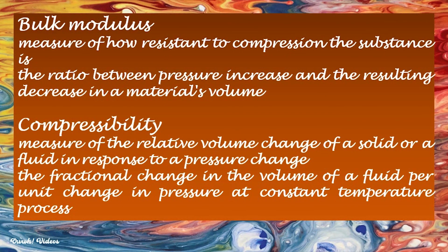Bulk modulus, a measure of how resistant to compression a substance is, the ratio between pressure increase and the resulting decrease in a material's volume. Compressibility, a measure of the relative volume change of a solid or a fluid in response to a pressure change. The fractional change in the volume of a fluid per unit change in pressure at constant temperature.